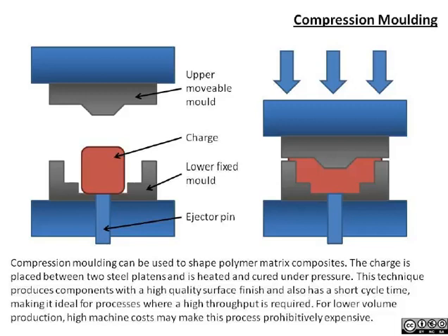It has some strength. It's sitting there. It's not pumpable the way the two-part reaction molding charge was. So it can sit in the mold, and this would be akin to high temperature forming for metals, where we mold it into place, and then by cross-linking it in situ, usually at high temperature, we achieve both shaping and properties at the same time. And this can be done in a fairly short cycle.